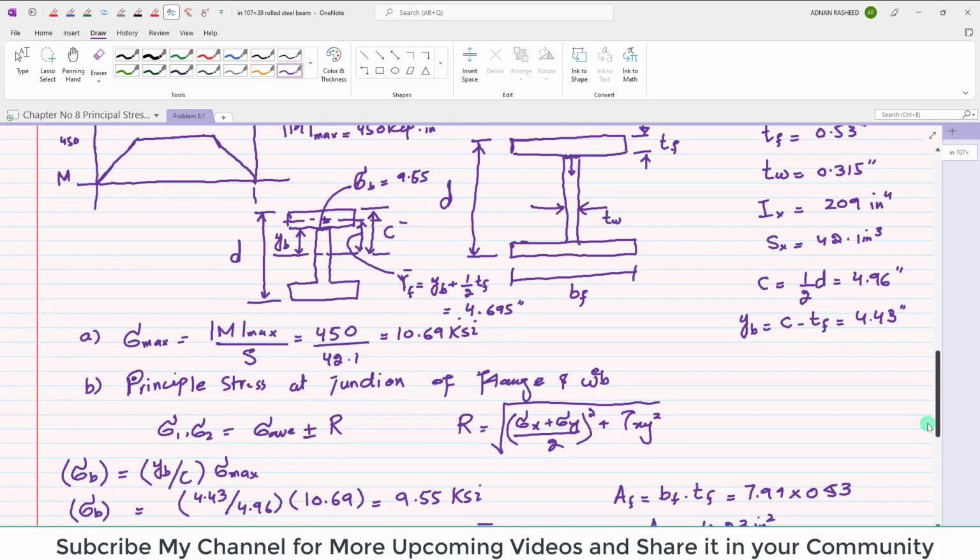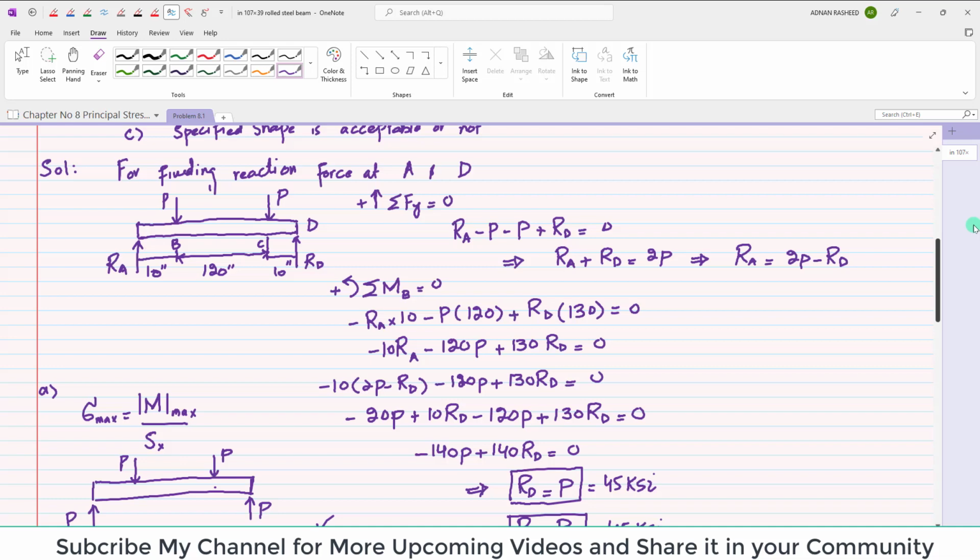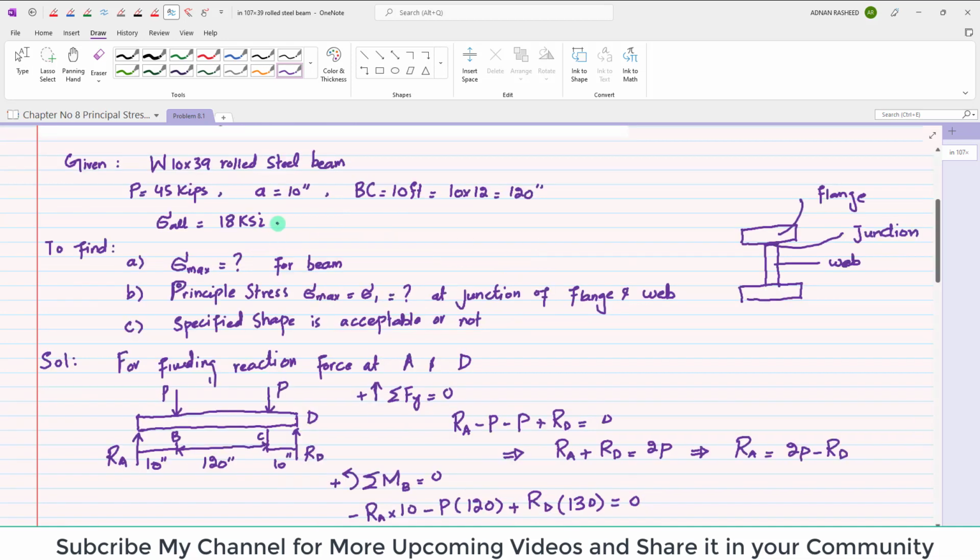Clear? Again, in part C, it was given to check whether the specified beam is acceptable or not. So you can see that your principal stress should be less than the allowable stress. So we will check sigma 1 is equal to 19.18 KSI. Clear? While sigma allowable that is given in the question is 18 KSI.